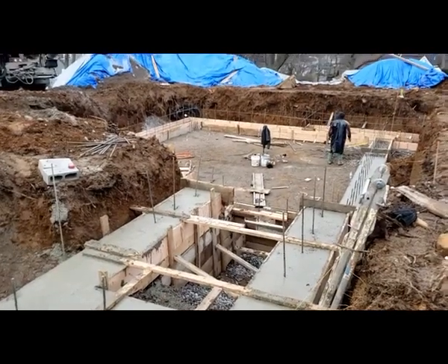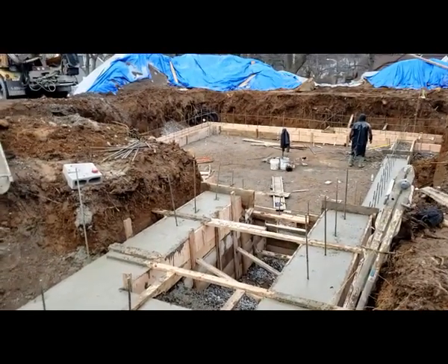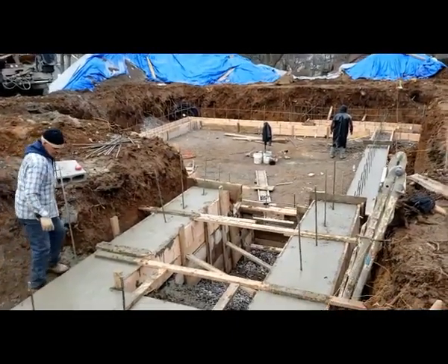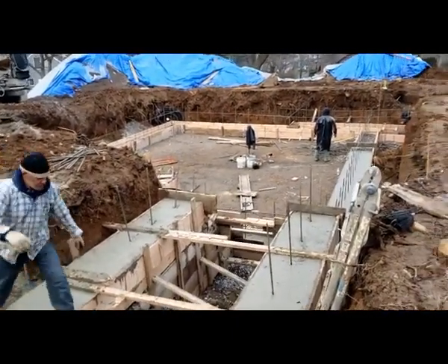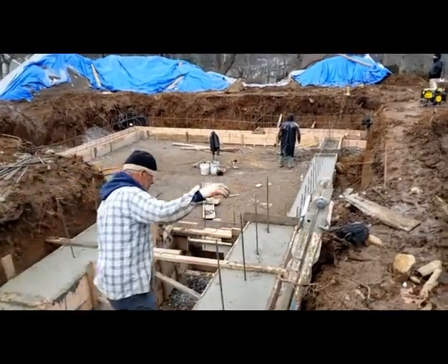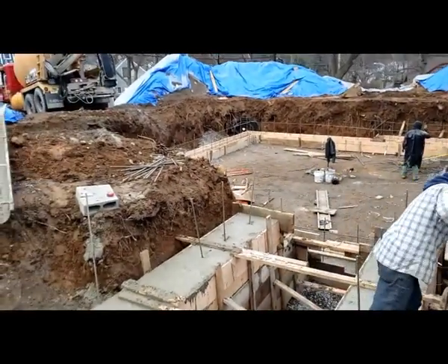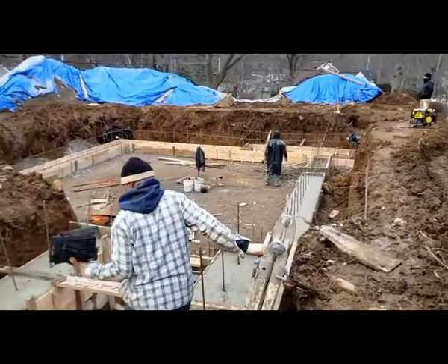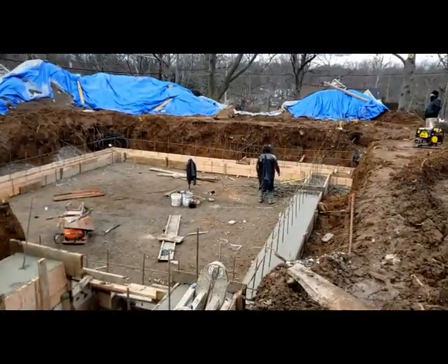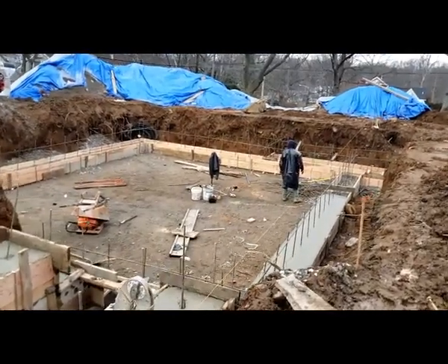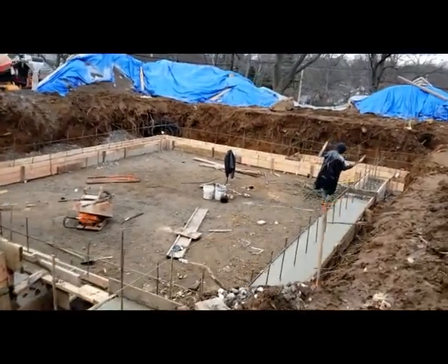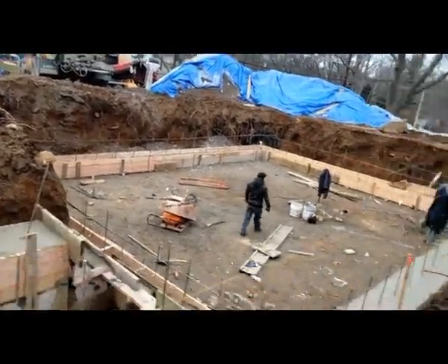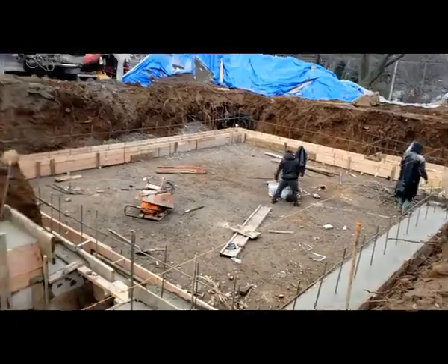Hey guys, so here we poured the concrete. We started pouring the concrete. We finished the back area. We still have to put some vertical rebars before the concrete dries out. Now make sure you space the 2 trucks about half an hour, 45 minutes max apart, so you don't have cold joints in the footing, and the concrete can blend and join together. So at this stage, once the concrete is finished, we're gonna have it nice and level, ready for the walls.